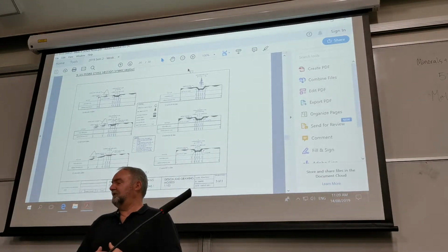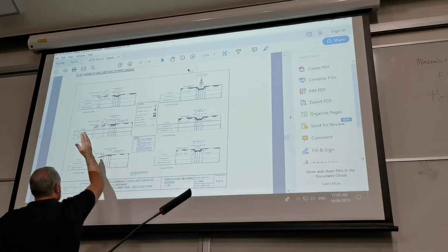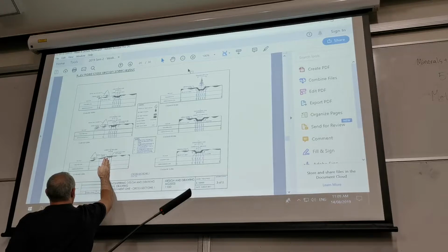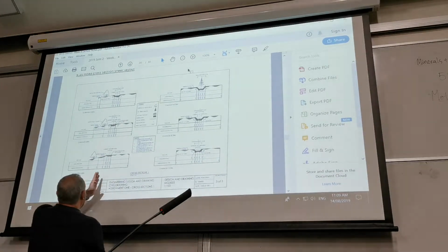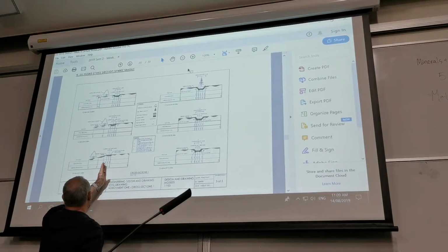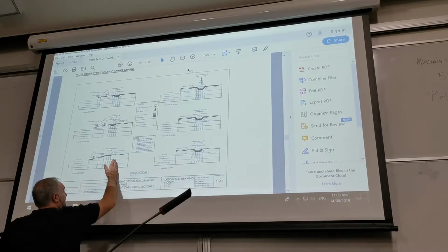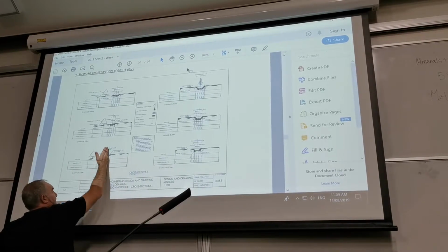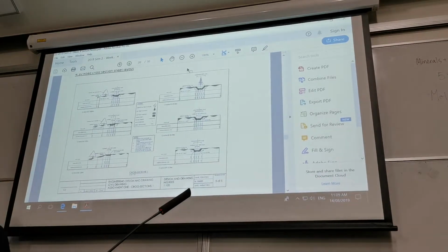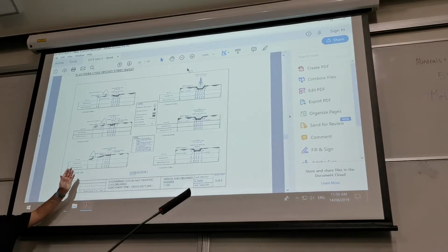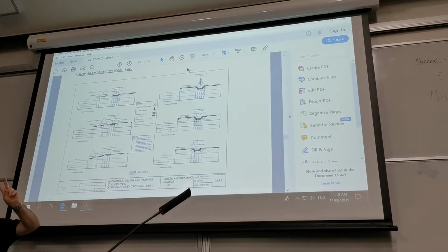When we draw the cross sections, we draw them up with the centre line being the point of reference on most roads and on your platform. Anything to the left, we call it distance to the left. Anything to the right, to the right. So this centre line becomes 0. Now that's quite different to the long section. In the long section, the 0 was at this end, isn't it? Yeah. Okay? So there's a second difference in cross sections.